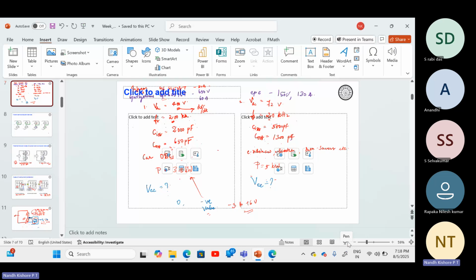One of the drawbacks of GaN, or I mean, not a drawback, it's just still in the research stage, is that you don't get GaN devices for voltages more than 650 volts. I think there is one 900 volt device available, but other than that you don't have a lot of options. So you can safely use them for low voltage applications, probably around 400 volts.